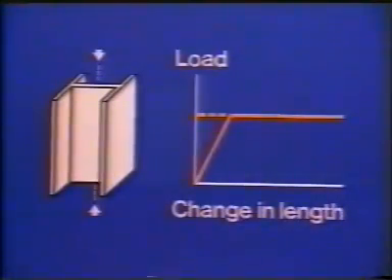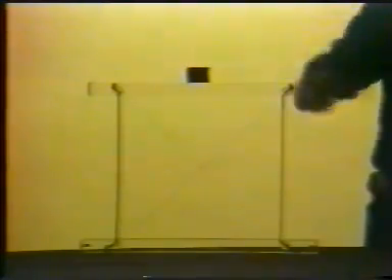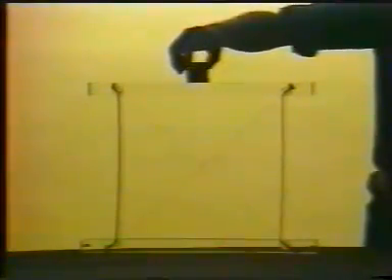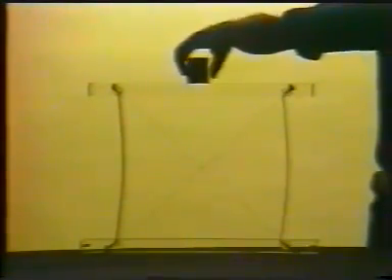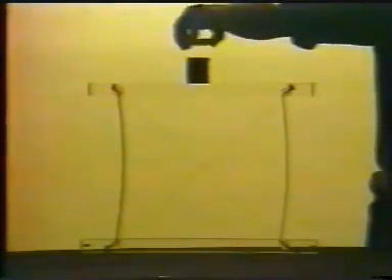The collapse load of a column is related to two limit conditions. A stocky column will fail by general yielding of the cross-section, and the column will squash. If a column's slenderness is very high, higher than is found in normal fabrication, it will fail elastically without yielding. If it is initially deformed, failure will be accompanied by a gradual increase of lateral deflections.